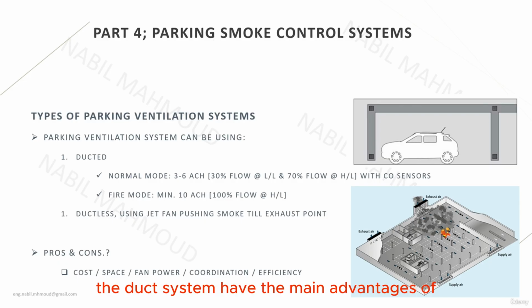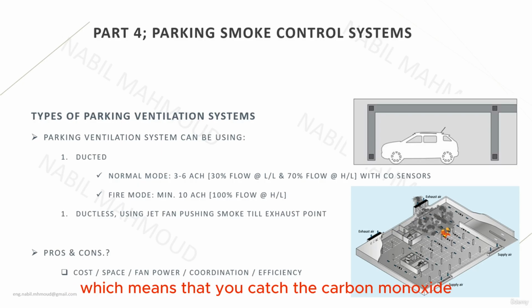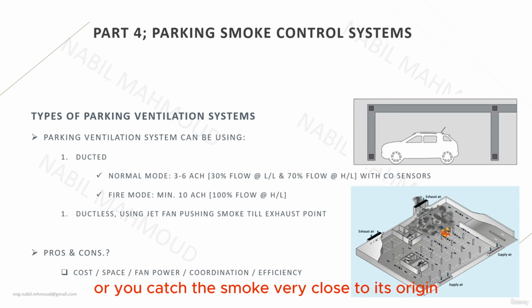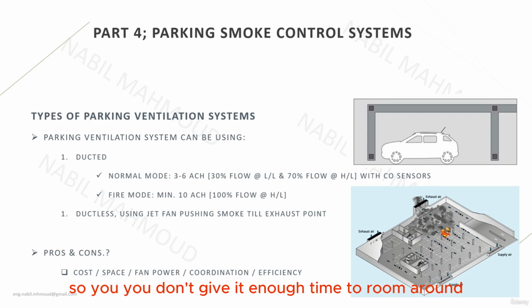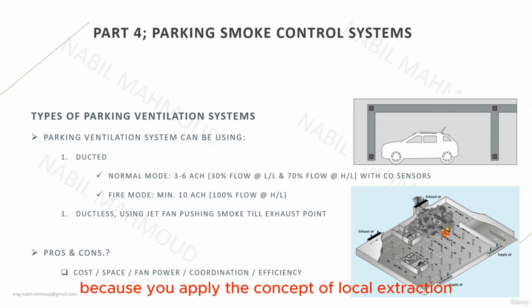The ducted system has the main advantages of achieving a proper distribution and of local extraction points, which means that you catch the carbon monoxide or you catch the smoke very close to its origin. So you don't give it enough time to roam around inside the parking. You prevent the smoke from spreading inside the parking because you apply the concept of local extraction.